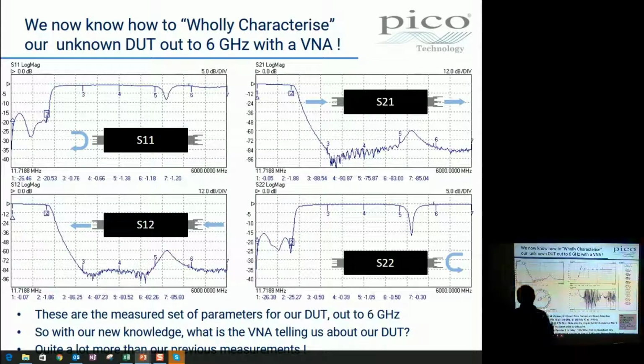So, does it make sense then, if you've only got access to one end of the device, to do an S11 time domain? Yes, you can. It does make sense if you're trying to find, say, distance to fault or whatever. And we did that. Well, no, we didn't. We did it with the 9311, didn't we? We saw a time domain response for S11, and yes, you can do it to S11. It was a straight line, and then it went ding, and then settled out, didn't it? Yeah, you'd get that. It does make sense. It was S11 that we were getting in trouble with.